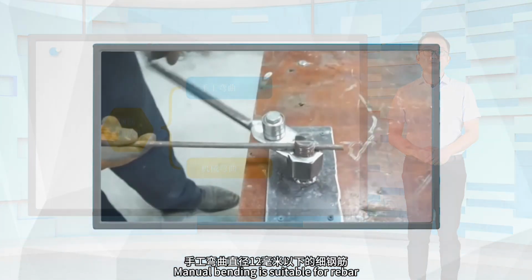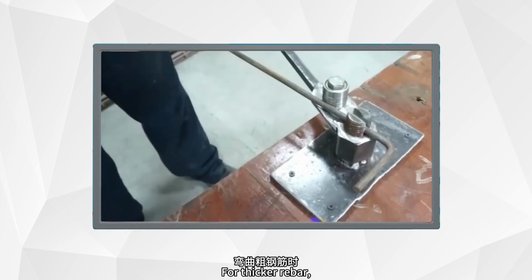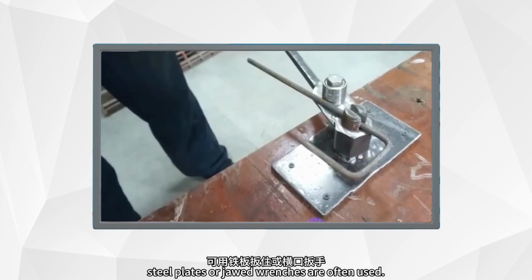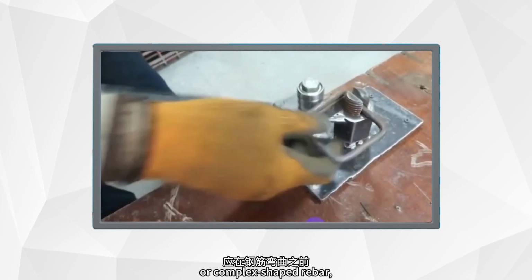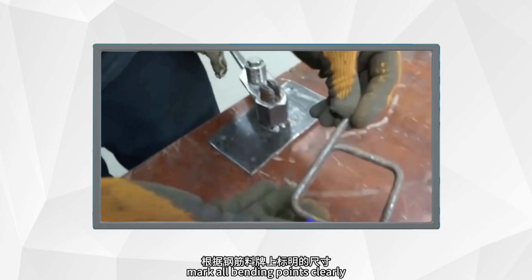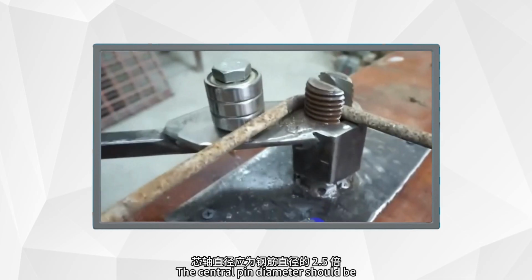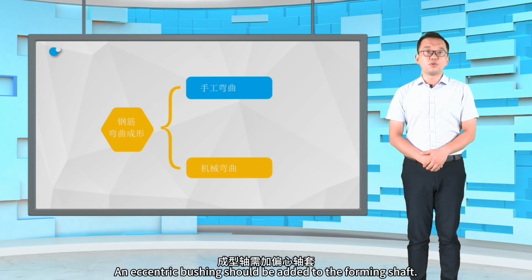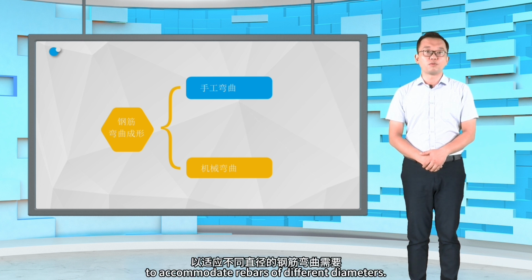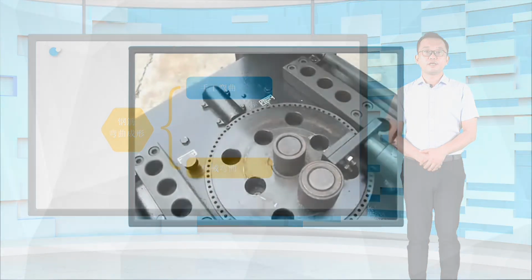Manual bending is suitable for rebar with diameters of 12 mm or less, typically using manual levers. For thicker rebar, steel plates or jawed wrenches are often used. Before bending thicker or complex-shaped rebar, mark all bending points clearly, according to the cutting list dimensions. When using a bending machine, the central pin diameter should be at least 2.5 times the rebar diameter. An eccentric bushing should be added to the forming shaft to accommodate rebars of different diameters. Last, let's watch a video of a rebar bending machine in operation.